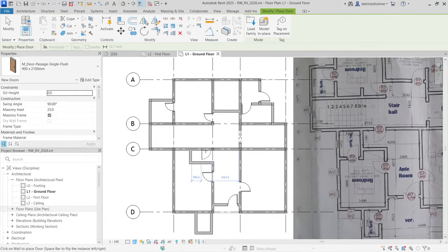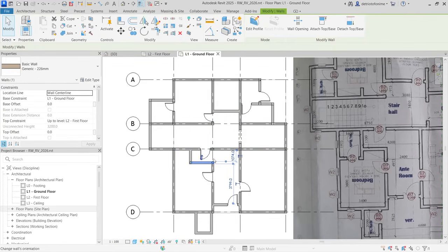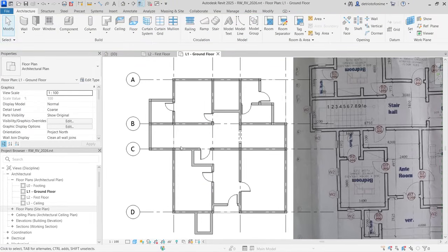Looking at the dimensions that we have on the floor plan, it doesn't really make sense when you model it inside of Revit. It looks like that space is really, really small to be 1003. So let's just select this space. It shows you that it's 1074, despite the fact that we typed 13. So you have to go ahead and type in 13 from here. Revit is going to adjust that. Let's make sure this is 16 as well. This is 1374. It's supposed to be 1600. So once you type that in, you've gotten the exact measurement that you're looking for.